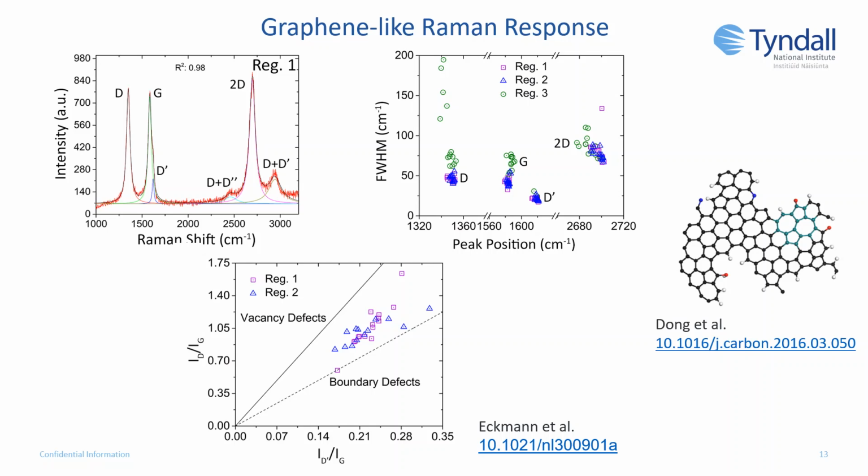As I also noted earlier, the formation process of laser-induced graphene is complicated and involves the loss of smaller molecules and reformation of carbon groups to produce a graphene-like material. However, as marked in the figure on the right by Dong et al., who modelled the process, there remains in the laser-induced graphene an unavoidable amount of unremoved groups, as well as structural defects like Stone-Wales defects. These are pairs of 2 heptagons and 2 pentagons in the place of 4 hexagons in a graphene sheet.